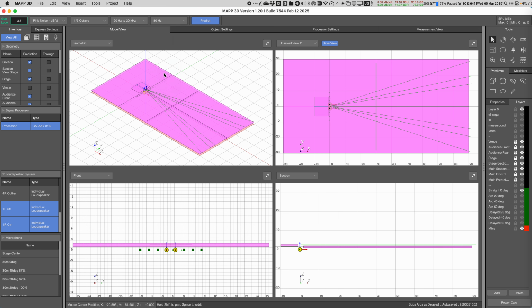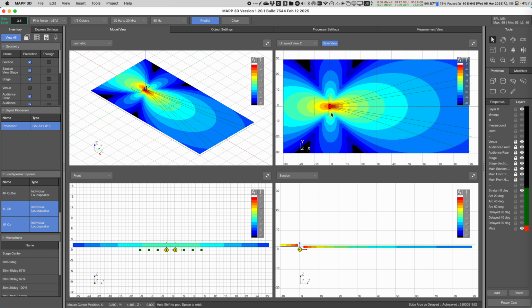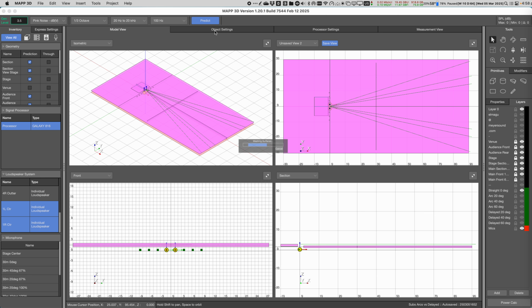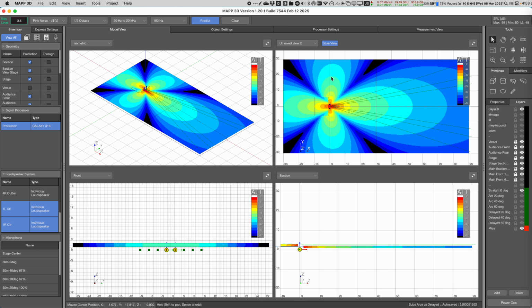But what happens if I now play this frequency? You start to see that, from the full darkness, we start to have a recovery. This is because we are having more than 180 degrees of phase shift, and we are going from 180 in the direction of 360. We are right now at approximately 240. Now we are around 270 degrees. You can see that this goes brighter in color.